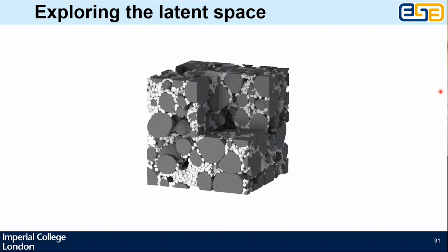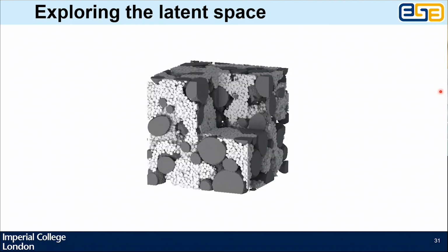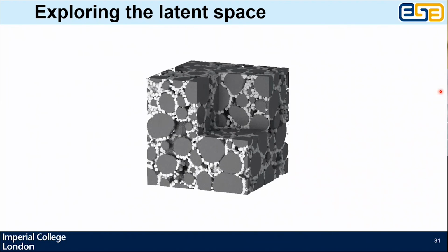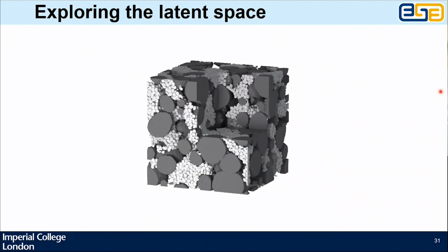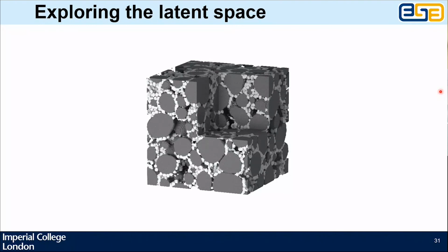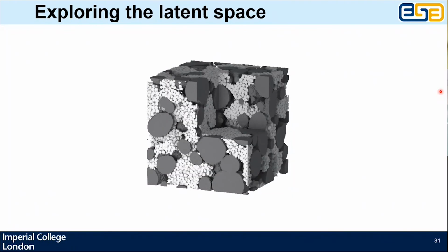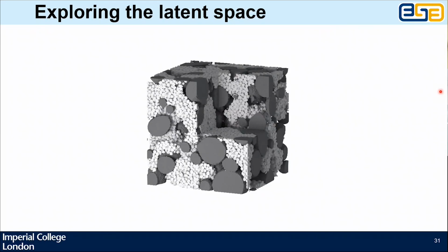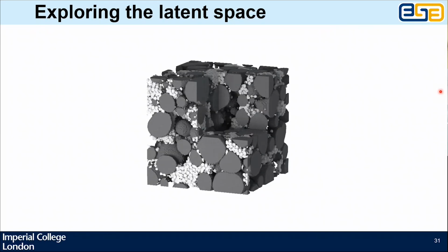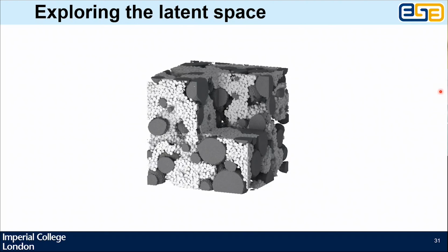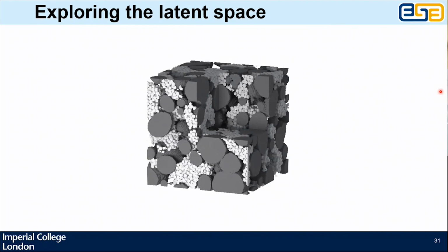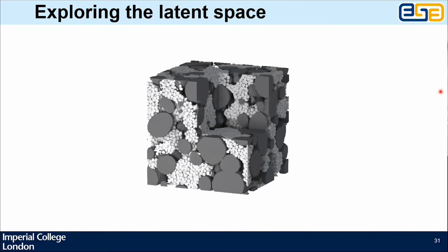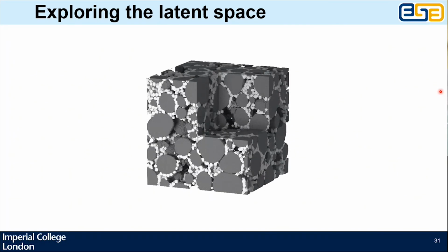That is, we think, a bit of a game changer in terms of, there are so many parameters that you might want to change when you're manufacturing battery electrodes. And so exploring that space is very important if you don't want to waste a lot of time in your factory. And so we have now got this design cycle where the slowest part for us is now the metric extraction. So even though that's been sped up by 3 orders of magnitude in our GPU accelerated tau factor, it still takes a few seconds to characterize a particular microstructure, which is what's slowing us down right now.